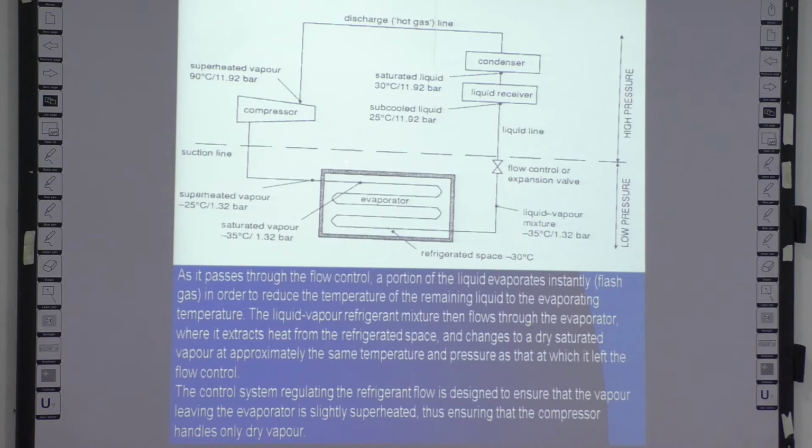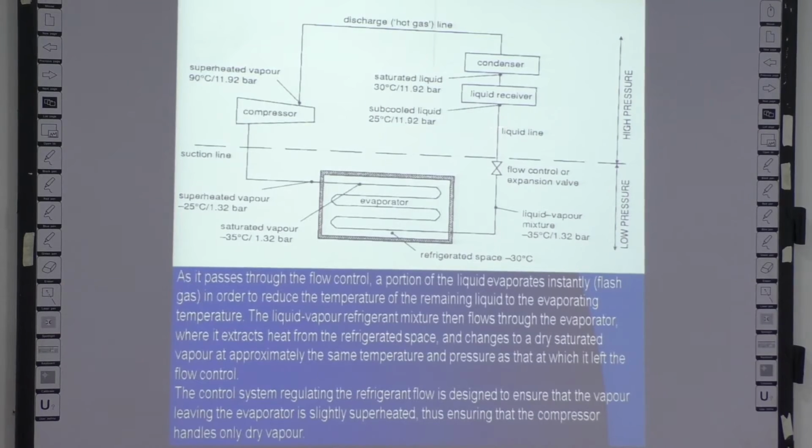Generally, the expansion in the expansion valve is considered an isenthalpic process. So if you remember this, after that it enters the evaporator coil, where the liquid refrigerant gathers a large amount of heat from the room and converts into gas, and as it leaves the evaporator coil its temperature is cold as it enters the compressor. If you have followed the energy levels now, I have explained everywhere where the energy drops and where the pressure drops. You could easily figure out how the pH diagram would be.